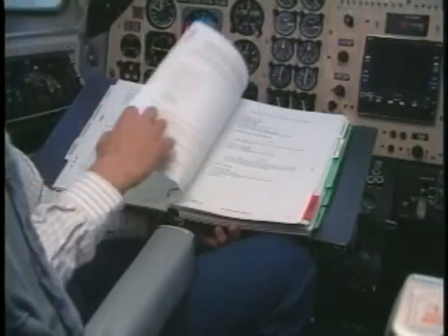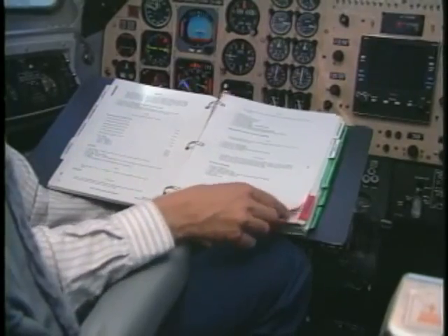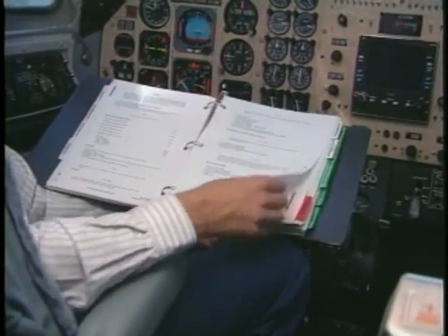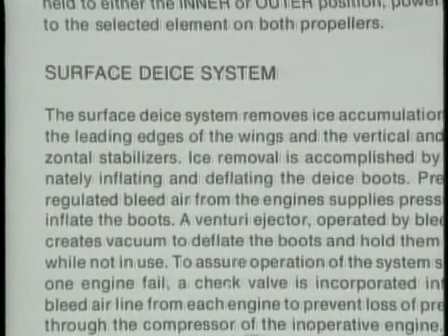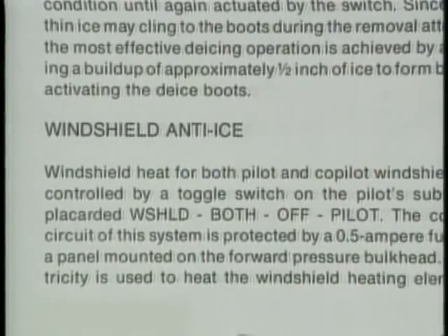Of course, flight in icing conditions may be hazardous regardless of how your aircraft is equipped. Before you enter areas of known icing, you should be sure that all of your systems are operating correctly and that you're familiar with the specific equipment installed on your aircraft. It's also a good idea to limit your exposure to icing conditions. Some of the systems described may handle ice better than others.